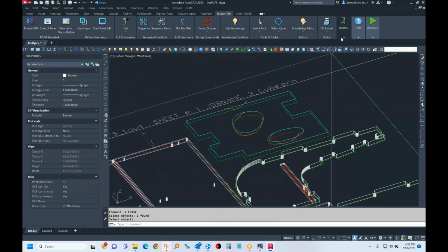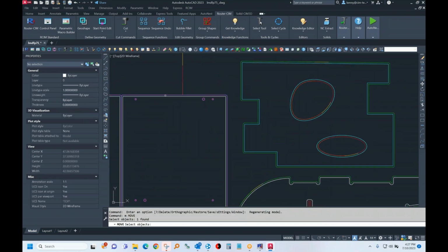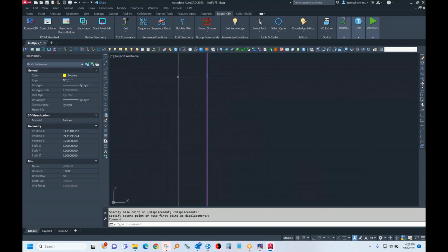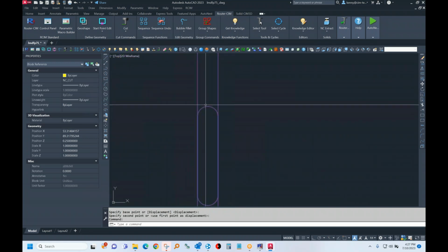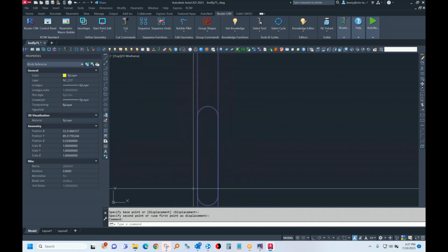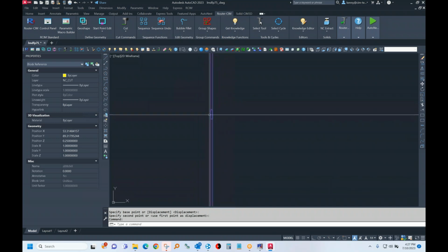Also, this toolpath that I made here is using a tool stay down nest. So this path right here is just one lead in and one lead out, and all the parts are connected together with a little overlapping bridge with an arc motion. So the tool makes an arc out and an arc into the next part, cuts around, then overlaps and arcs out and arcs into the next part. Much smoother, much faster. That's version 3 of the stay down.